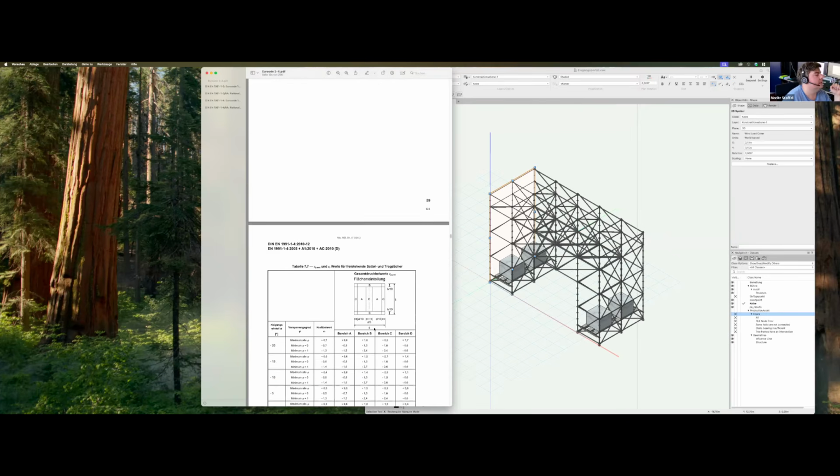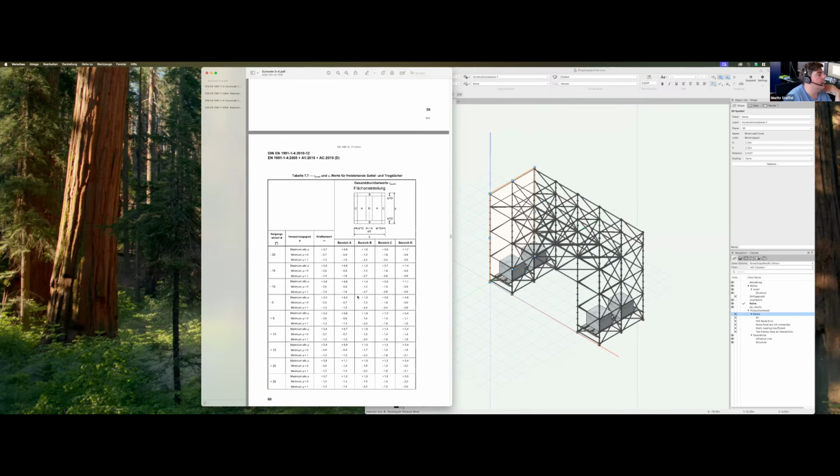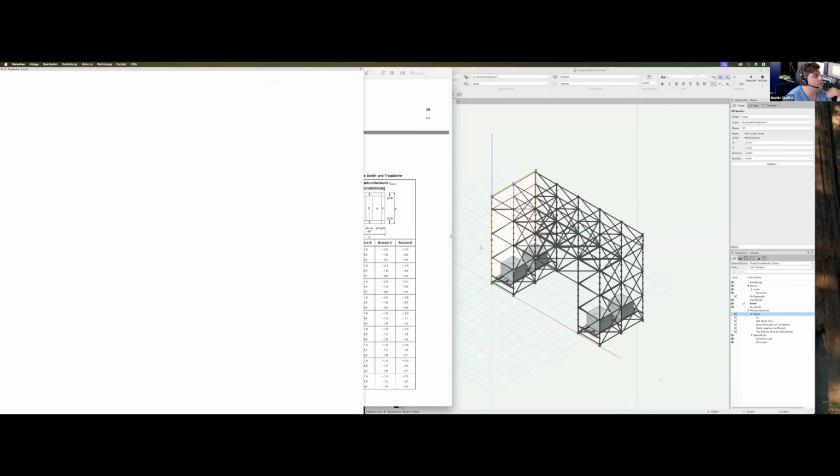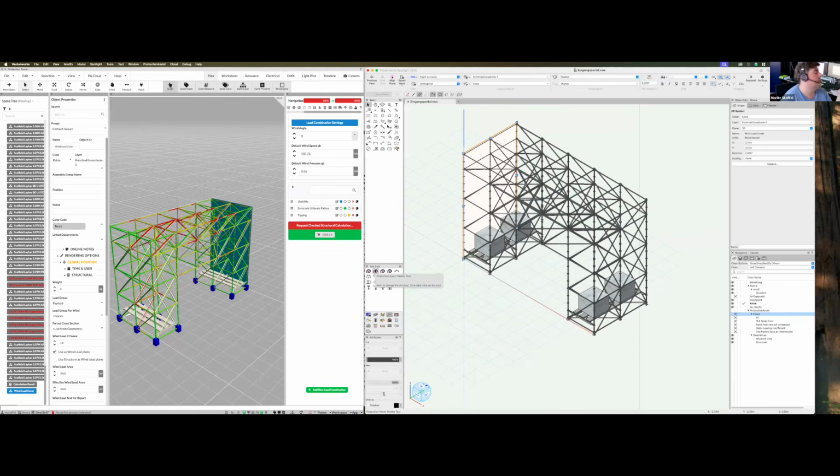So the problem is it takes quite some effort and some knowledge to put them in place. So the wind load factor 1.8 is actually quite high. So it's a good starting point if you're not really sure what you're doing, to get an idea of what could happen. Normally it's possible to reduce this. We're working on tools that make it a little bit easier to calculate this, but this is not currently in this update, not in the next update, but it's planned for the one after. Does this explain a little bit for you?